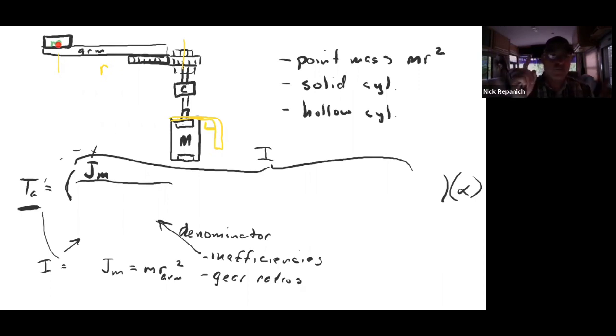From the motor's perspective, you have two things that are moving at different rates. There's an inefficiency there. The next thing that you're looking for is gear ratios, because that changes the inertia significantly for us. So let's walk along here. We're the mass. First thing we do is we'll jump down onto the arm. Was there any discontinuity there? Are those two moving the same? They're moving the same, right? In fact, here's another way to think about it.